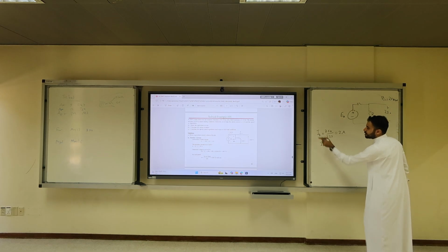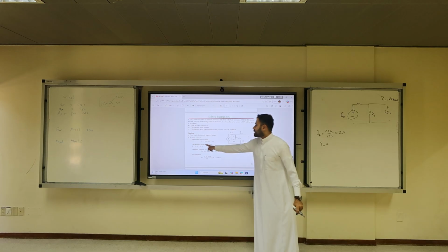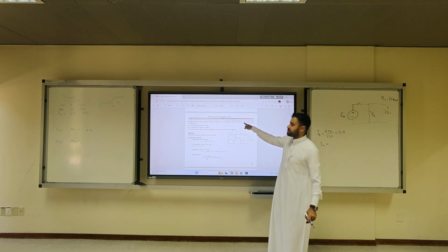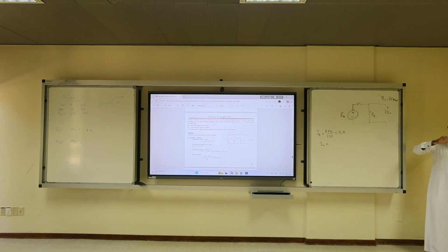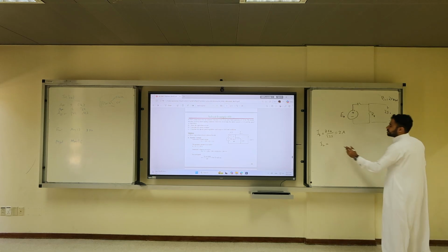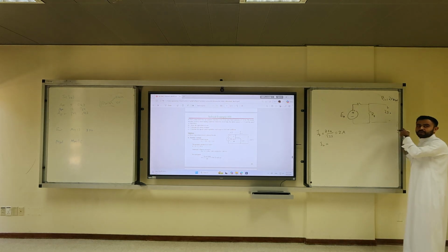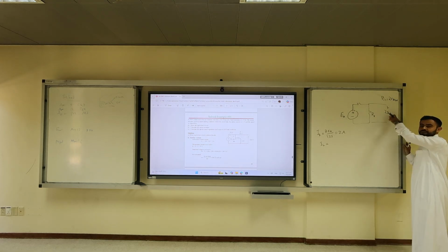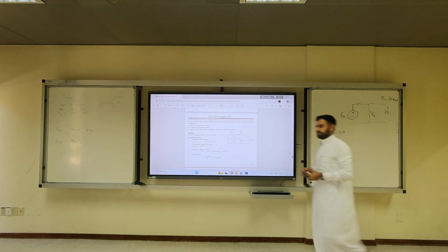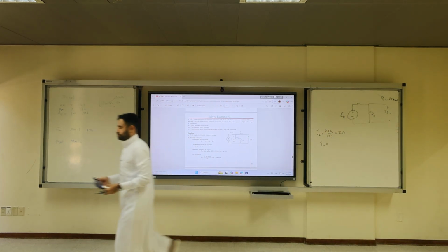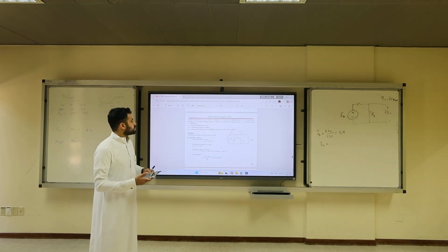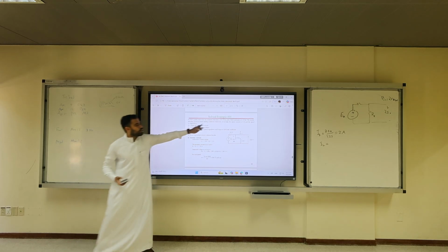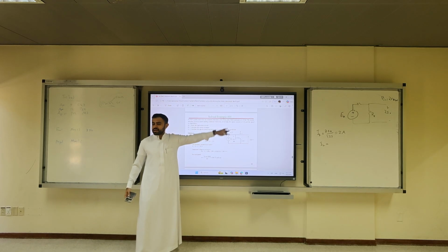So I line, you get the I line from where? You get I line from the problem statement. Sometimes you get it from the power factor, loading, etc., if it's AC, but this is DC. Or sometimes you get it from the input power and the input voltage, which is 25 kilowatt over 250. How much is that? 100 amps. So this is at full load. Full load current is 100, okay?